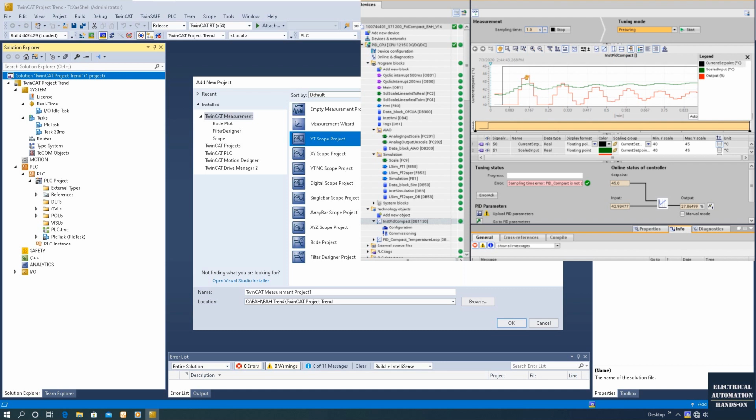Because of this, storing long-term data isn't available using the trace function in TIA Portal. Basically, this trace function is used for troubleshooting, recording data within 1 minute, usually for troubleshooting the signals or the timing chart. For example, if a sensor has a flickering signal, this trace function can show the issue very clearly. This is Siemens TIA Portal.